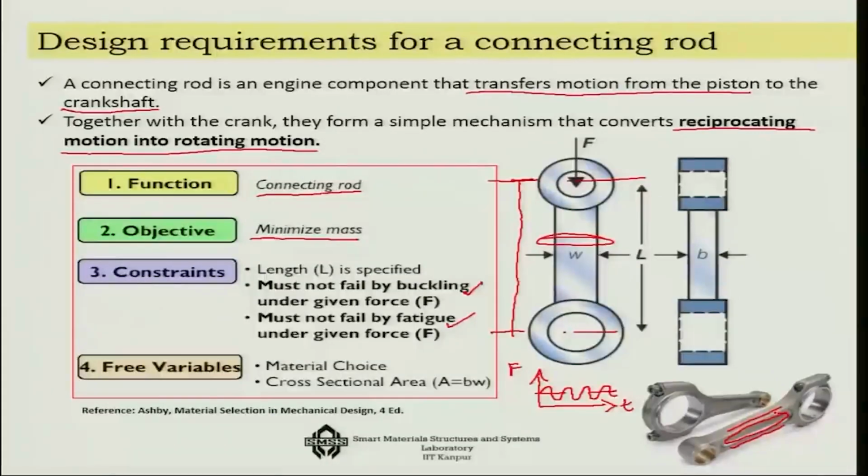One is in terms of controlling the natural frequency, so I will not talk about it today, but the resonating frequency is also of concern. Hence if you reduce the mass, the natural frequency of the system, which is square root of k by m, goes up as you reduce the mass, so omega goes up and this fellow would not resonate. So that is one of the strategies that they take.